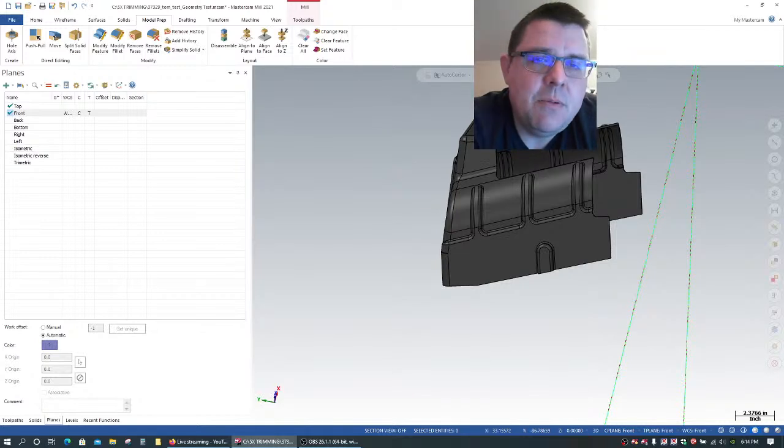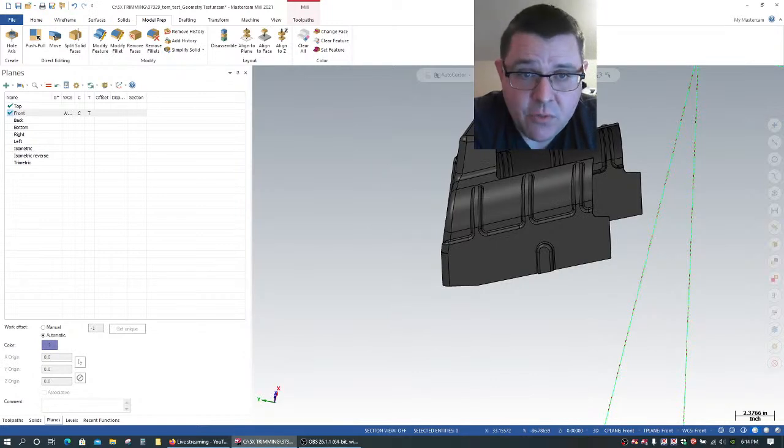One of the things you have to keep in mind is that with Mastercam, the operations themselves may have multiple tool changes inside the operation. So for example, contour toolpath. If you had depth cuts or if you had multi-passes, each one of those passes is what they call a null tool change operation in the post.